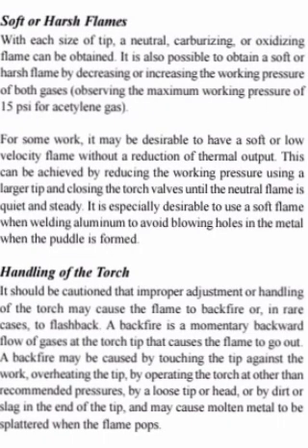Handling of the torch. It should be cautioned that improper adjustment or handling of the torch may cause the flame to backfire or, in rare cases, to flashback. A backfire is a momentary backward flow of gases at the torch tip that causes the flame to go out.